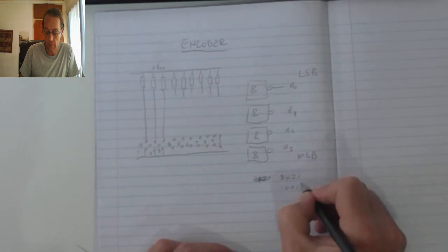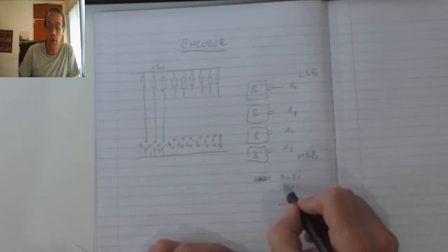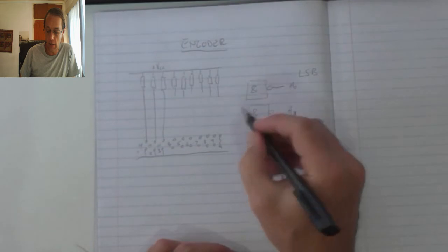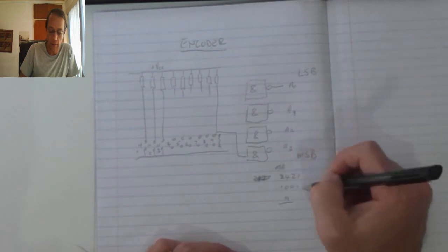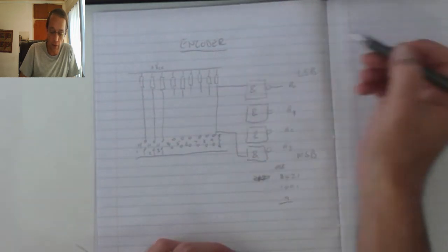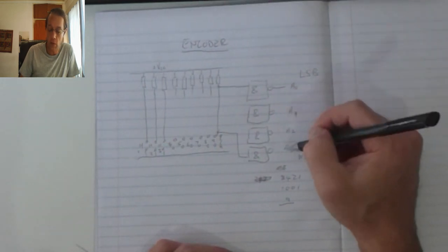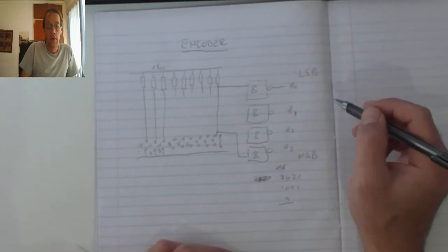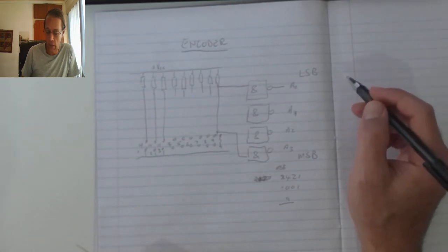Now if we look at a binary number, for example 1001, we can see that, in the 8421 code, it's 1 plus 8. That gives me a 9. So that means that my most significant bit, which is this one, must then connect to there, and my least significant bit must also connect to that line. And in doing so, I can then convert all this information into something useful that counters and adders and data input units can use at a later stage.